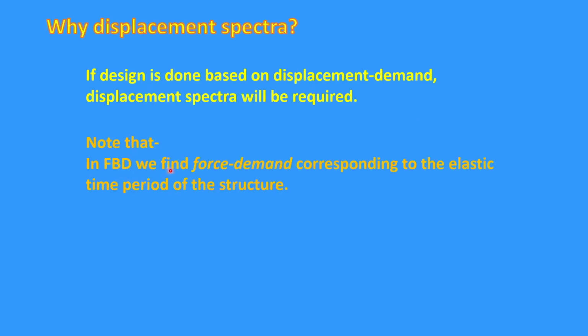In force-based design, we find the force demand corresponding to the elastic time period of the structure, as we have discussed. On the horizontal axis of the codal demand diagram, the design spectrum, time period is given. Corresponding to the time period, we find the spectral acceleration, and the spectral acceleration will lead you to the amount of base shear.